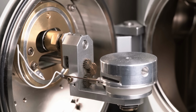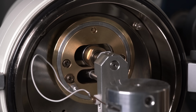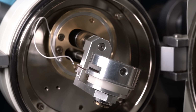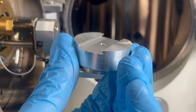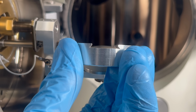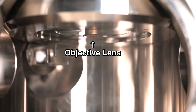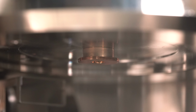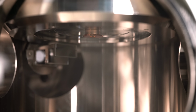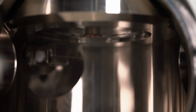This stage is fairly simple and has the ability to move forward and back, left and right, and also rotate and tilt. This stage also has this little dovetail joint that allows us to slide different sample holders on and off quickly and easily. The next thing to note is the objective lens here. Most of the lens is not visible from here, but you can see this copper-colored bit. That's the objective lens aperture holder, and it's the lowest part of the lens assembly. Anything we add to the chamber must clear that piece, or we will damage the SEM.